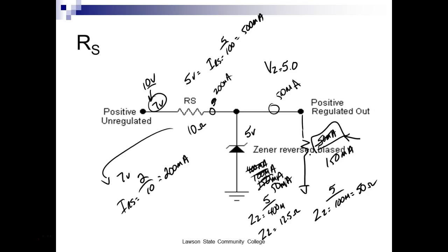are resistors rated in? What's the two main things? Don't say tolerance. Everything's got a tolerance. So every component we have has a tolerance. Besides the tolerance, what are resistors rated in? If I buy a resistor, if I look up a resistor, what's it rated in? Ohms and, guys, this is something y'all should know. Ohms and what's the second thing? No, they're not rated in current. Watts. There's the two things they're rated.